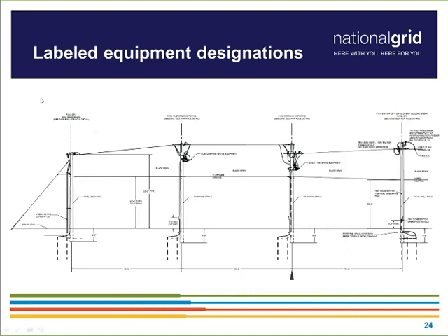So having the equipment such as your recloser, if you have one, labeled, fuses labeled, the gang-operated disconnect switch would get a specific label, and typically each pole would get a label. And again, those labels would be able to be traced back to an operator diagram and utilized for switching or communication purposes well into the future that extends past just the initial construction period.